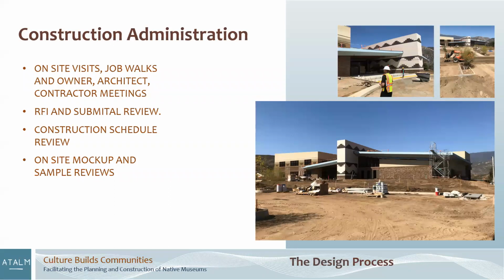Now, the legalities of it is, I need to document that and put it back into the set, but to have someone be aware and not be confused, confusion is a death blow to any process. So in this, on-site mock-ups is when we come in on this too, and sample review. So I'll review tile samples, but on the site, sometimes we'll do a full wall mock-up where we might have the base material below, we might have the upper material, we'll show tile coming in, we might even have a roof piece coming on.